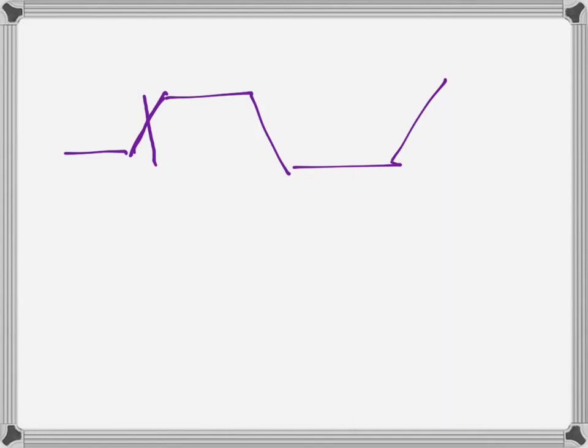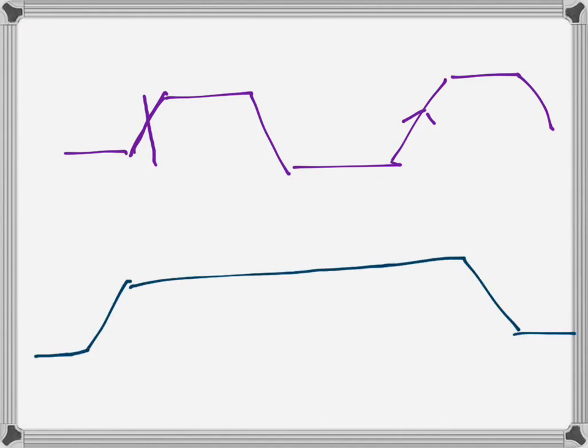For this type of clock, all the signals will be like that. The input signal is also like that, maybe like that, it changes like that. Then we also take the 50% point here. The 50% point of the input signal and the 50% point of the clock edge, the difference between them has to be more than the setup time. So that is setup time.